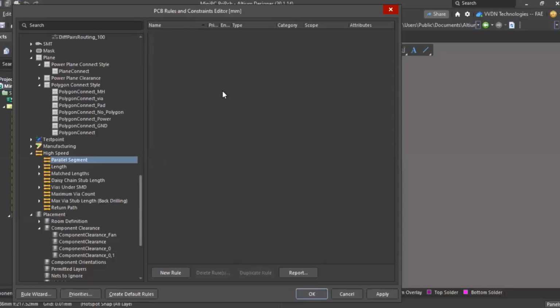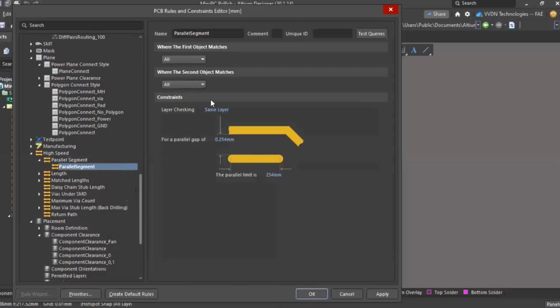Basically, we should not go with that, but in worst case, we will go, right? Means signal layer next should be the reference plane layer, but sometimes we will have one more signal layer adjacent to it, right? In that case, we should verify the parallelism, because parallelism again affects the signal, right? So we have a parallelism option, and so like this.